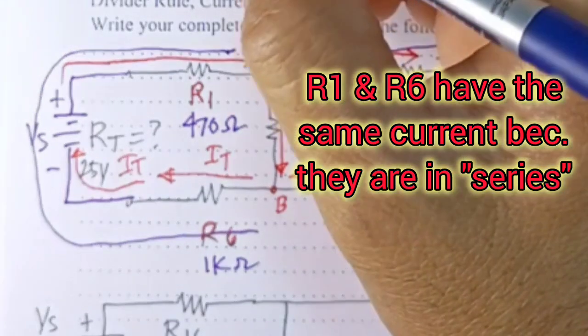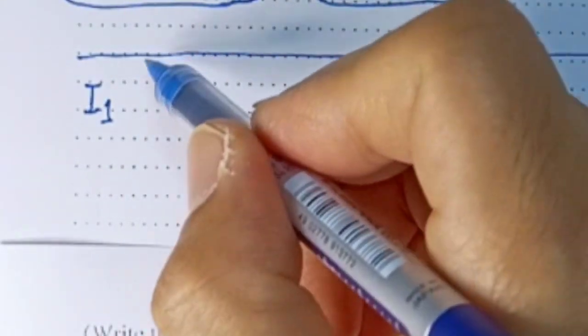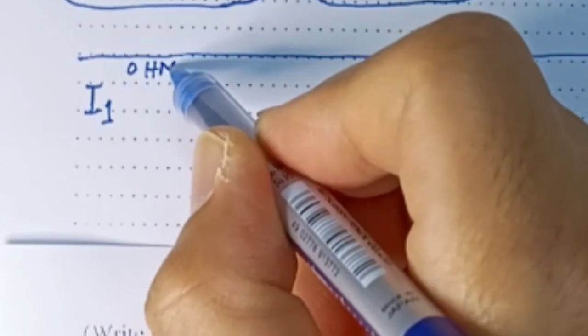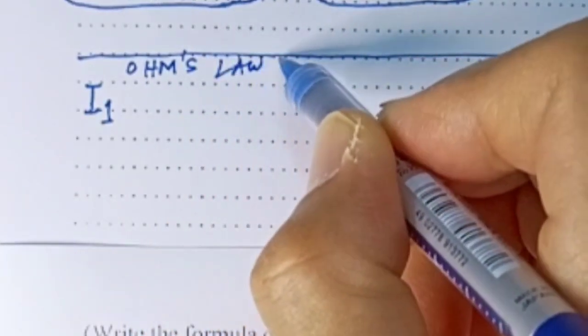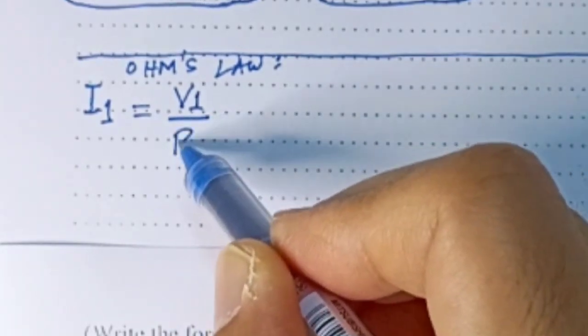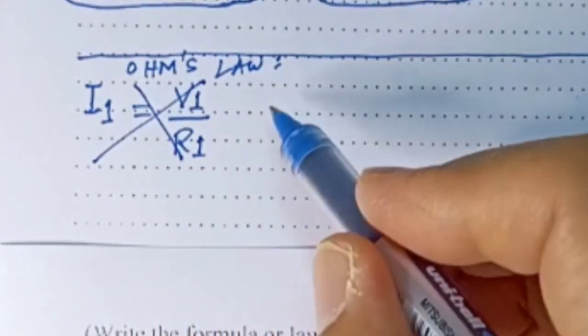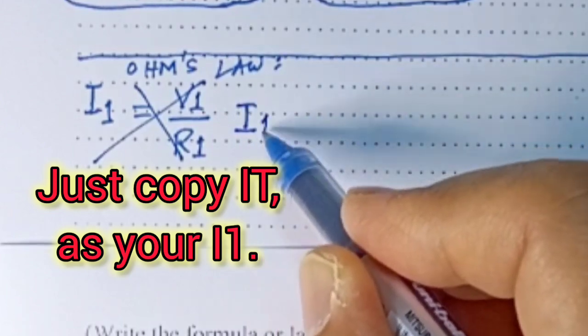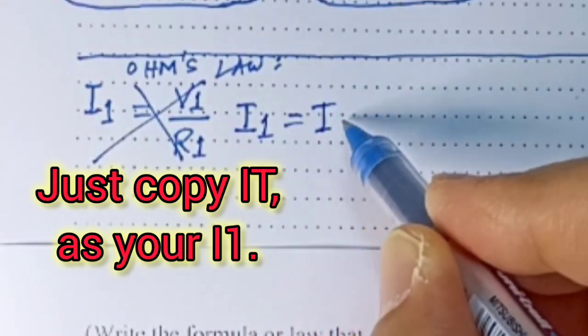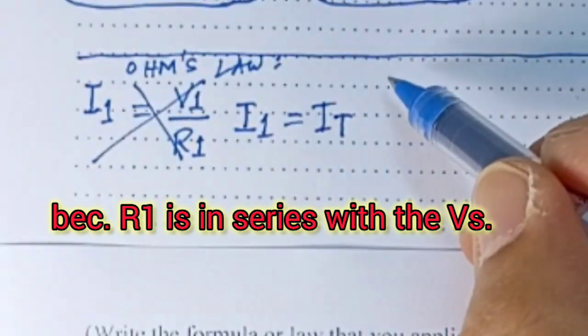And because of that, we can say that the current on the resistor R1, by using Ohm's law, we will get the current equal to V1 over R1, right? But we don't need to do that because the I1 will be equal to the I total because there will just be a single current in series.